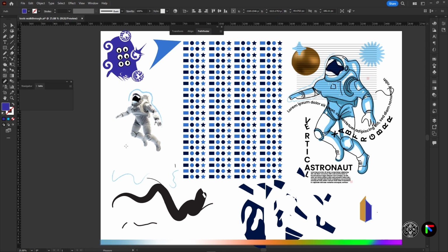And then we also have the measure tool. The measure tool helps you to measure distance, right? From one object to the other or from one space to the other, basically. And then you're going to have the information right here. So I can decide to say, okay, I want to measure here to here. And then I get the measurement, right? I can decide to measure from maybe this part of the screen to this part of the screen, holding my shift to constrain the straight line.